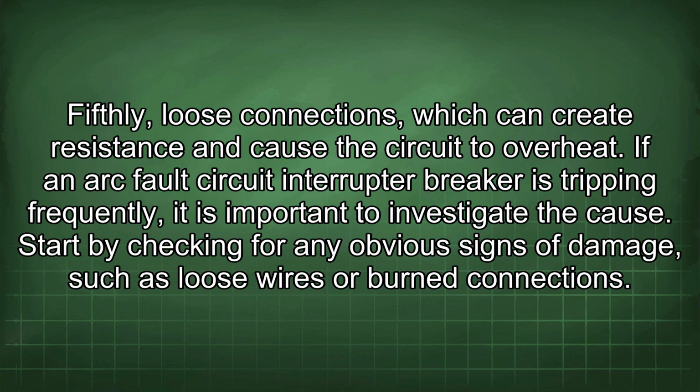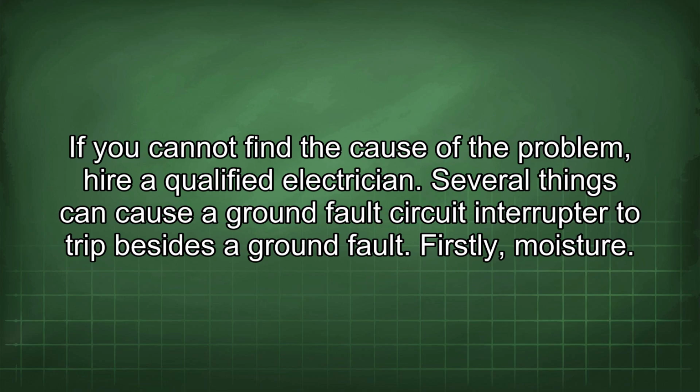If an arc fault circuit interrupter breaker is tripping frequently, it is important to investigate the cause. Start by checking for any obvious signs of damage, such as loose wires or burned connections. If you cannot find the cause of the problem, hire a qualified electrician.